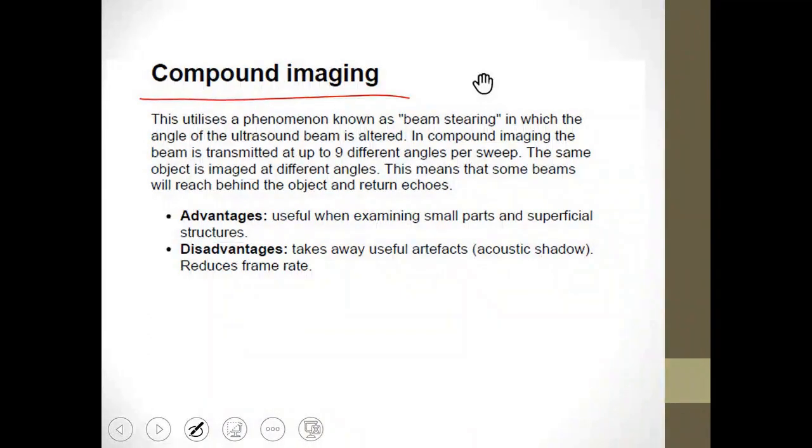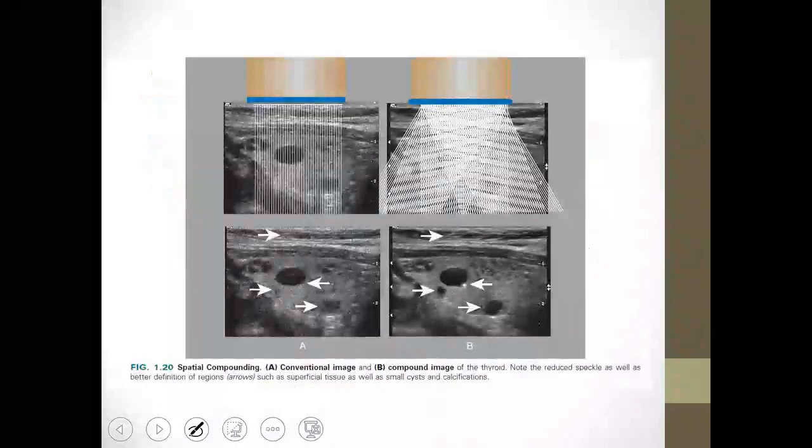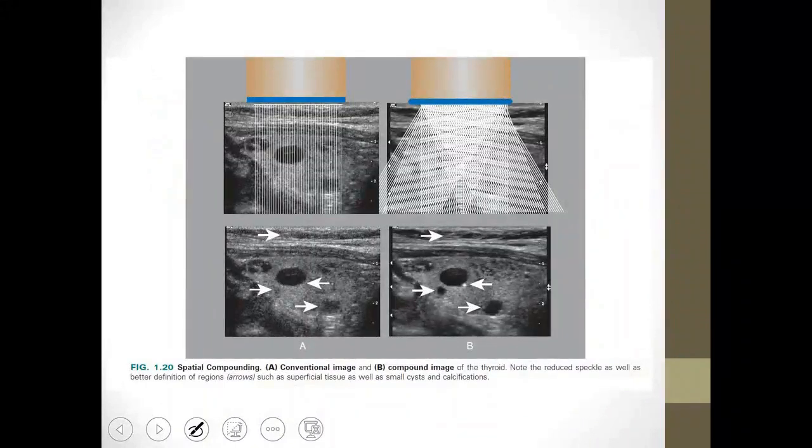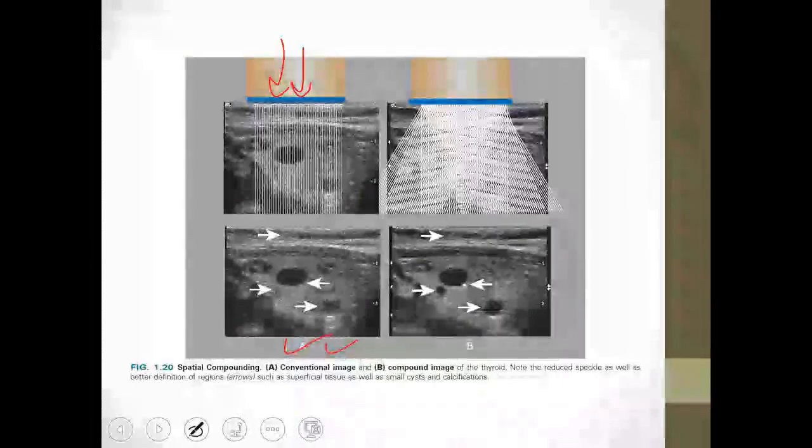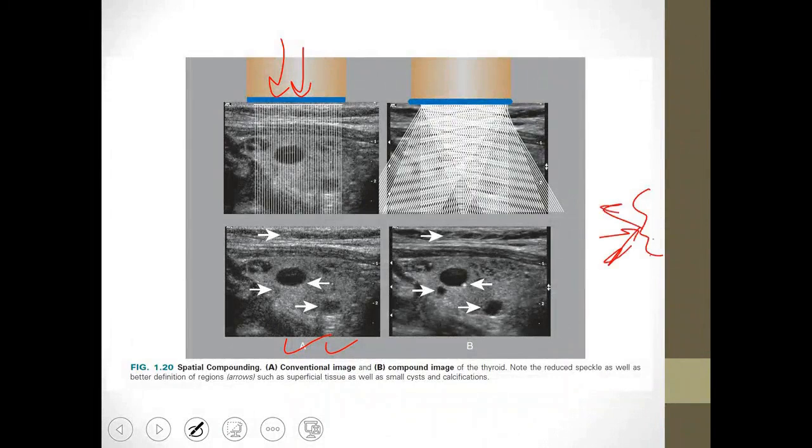You perform an imaging process that involves different operations. If you take a single view or angle for the transducer in this way, you get an image like this. If we remember, some of the rough surfaces where interactions occurred, with the ultrasound pulse, appeared as if they were noisy on the image. This means the image looks a bit noisy in these areas due to the scattering that occurred, which is referred to as speckle scattering.